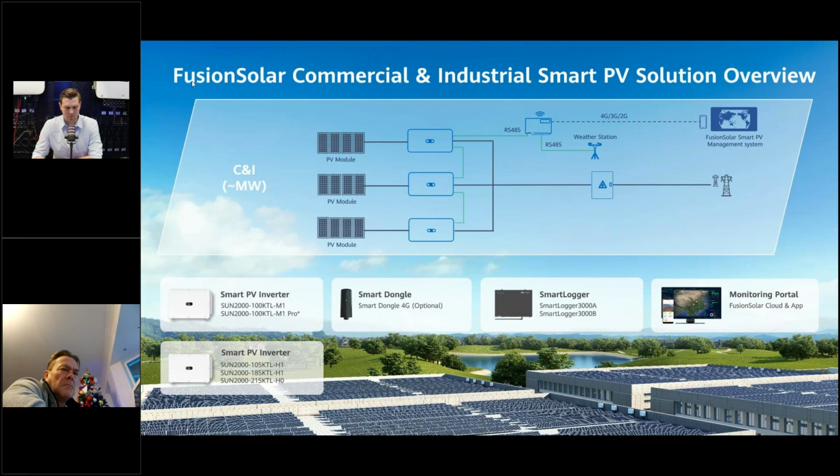So 215, and for a 1 megawatt PV installation, 4 of them is quite enough. You don't have too much DC to AC side oversizing. You don't have more losses from oversizing than is necessary in that case. So this product becomes very, very popular right now.